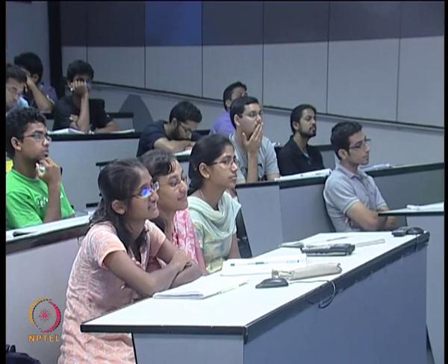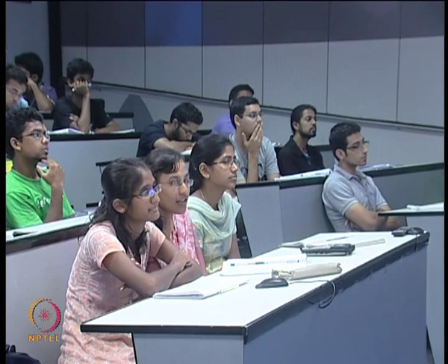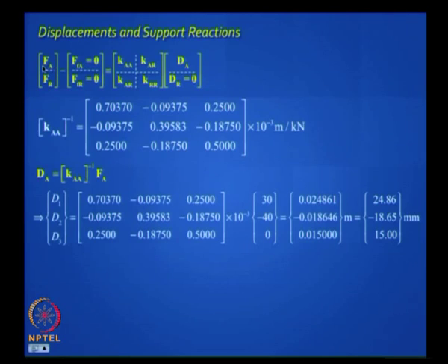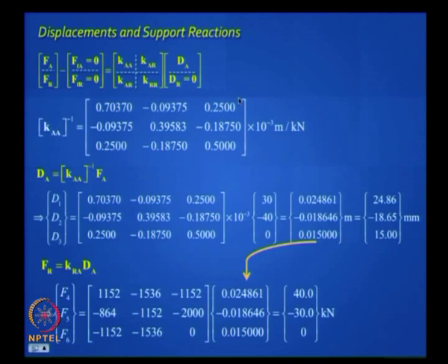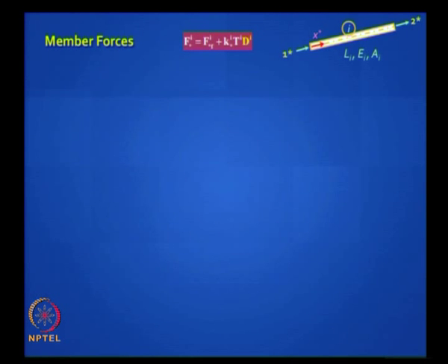Internal forces come later, you need to get the support reaction from the second equation. See, you got 2 equations here. After you get this, apply that in the second equation, find Fr, and you know those answers because it's a simple answer, it's 40 and minus 30 because it's statically determinate. Then you find the bar forces. Okay, you can actually check out sigma fx equals 0, sigma fy at this stage, which you should as an engineer. Make sure equilibrium is satisfied, and then what? Find the bar forces. How do you find the bar forces? There are no fixed end forces, so